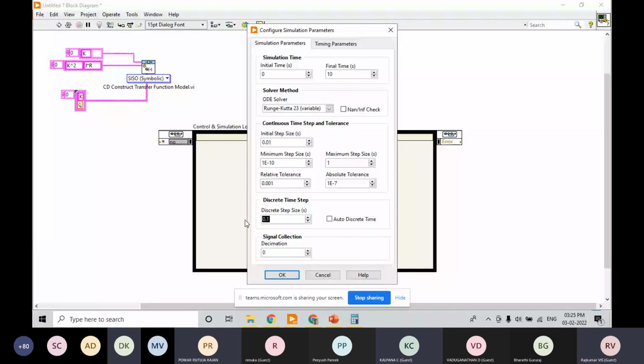So let's say I'm going to run this at the rate of 1 megahertz. So I have to give it in terms of time, 1e-6. And here I want this to happen in my control. It should not be like 1 to 10 seconds only. I'll keep it as infinite such that the control is in my hands. Let it run continuously. I should be able to control it.